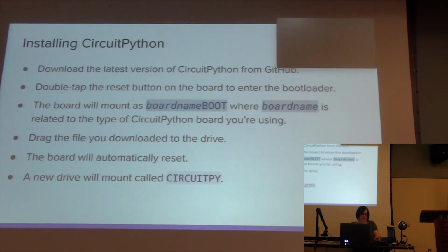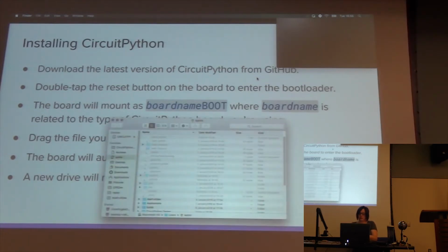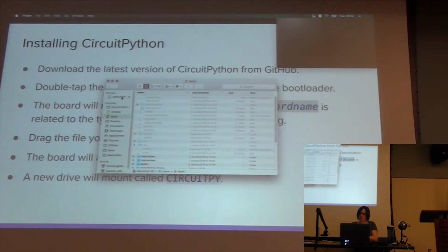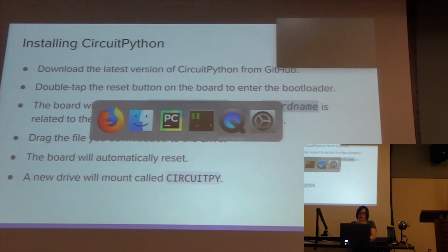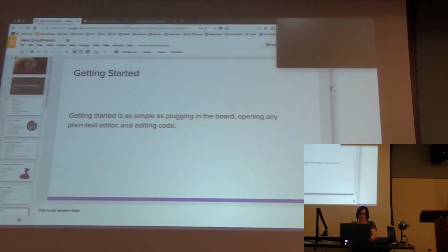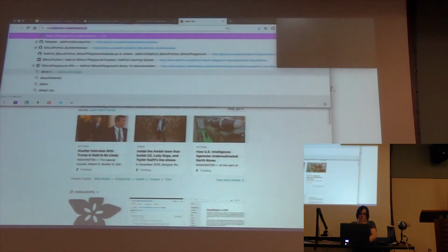When you enter the bootloader, it will mount as a drive called board name boot, which essentially looks like whatever name the board is. So this is a Trinket, so it's TRINKETBOOT. This would be CPLAYBOOT because it's Circuit Playground Express. You're going to drag the file you downloaded to the drive. It automatically resets, and CircuitPython is installed. Your drive will show back up again. So let's go ahead and...